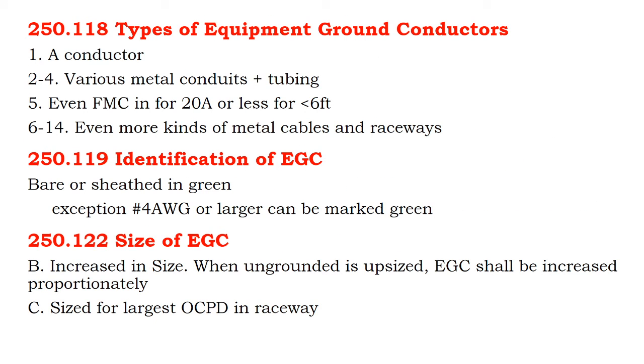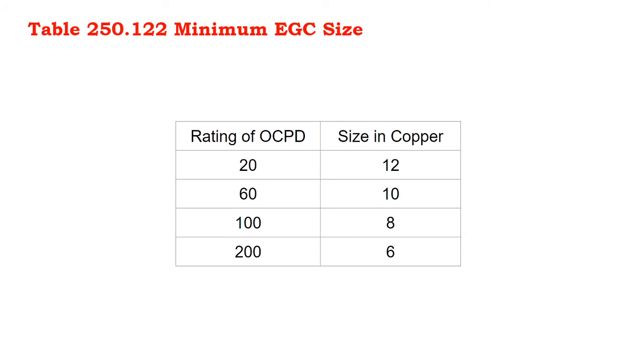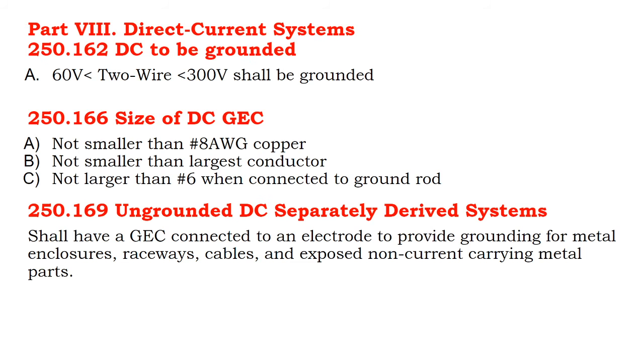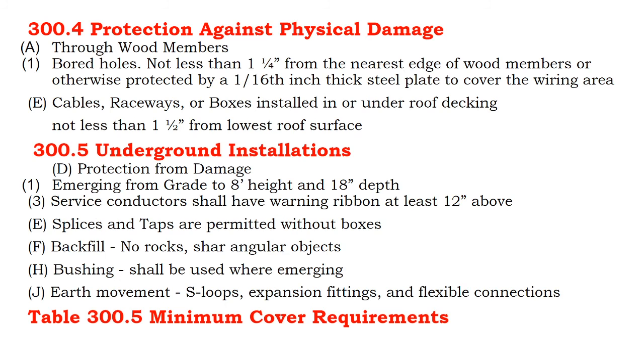But let me just preview what the rest of this program is. So you're going to get your 2 hours of credit. If you want to come back to it, you can. But basically what the rest of the discussion is, we'll talk a little bit more about grounding sizing and equipment ground sizing. Just to kind of jump up and down on saying you just run number 8 up to the rooftop, or number 6 if you're not in conduit.